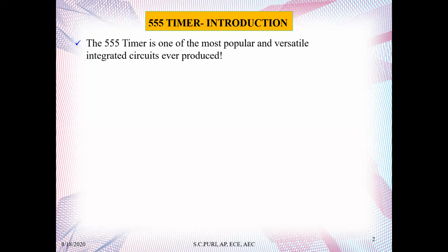Now we have discussed the monostable and the astable multivibrators. Because it can be used in a variety of applications, we have discussed things like one-shot or wheel timer, pulse generation, LED lamp flasher, alarm, tone, logic clock, frequency division, power supplies, converters, and a lot of other applications.